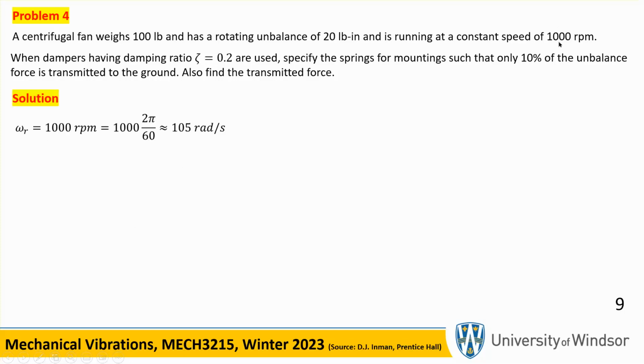The 1000 RPM is that many radians per second. The mass is in the units of slinch. You take the pounds, 100 pounds, divided by, if you wanted to get it in slugs, you divide it by 32.2. If you want to work with inches and things like that, divide by 32.2 times 12, which is 386. So it's that many slinch units of mass.